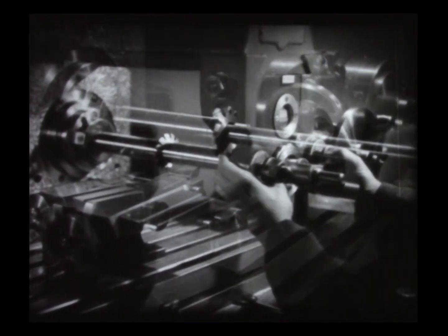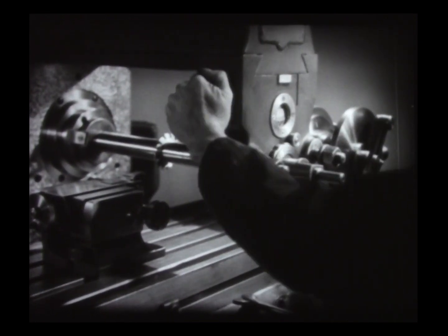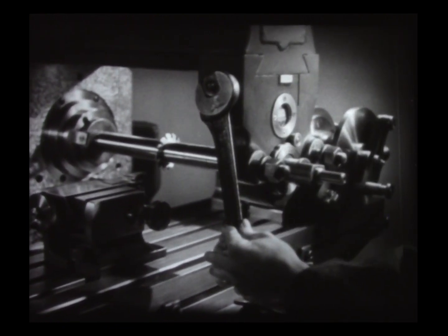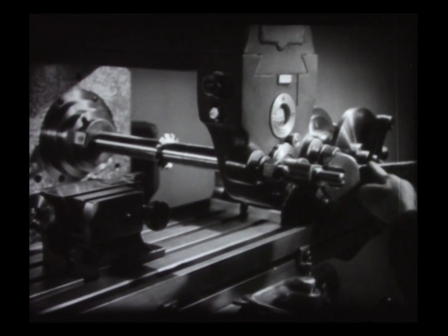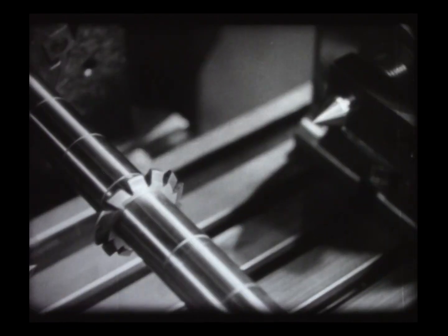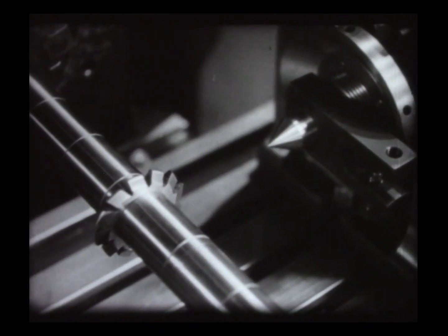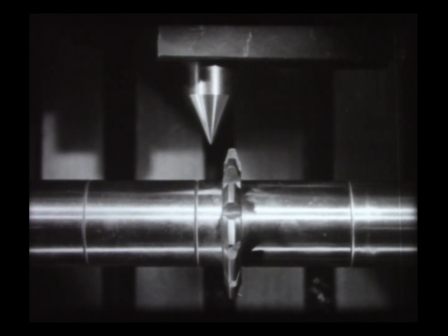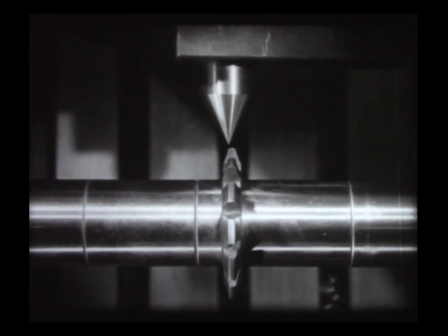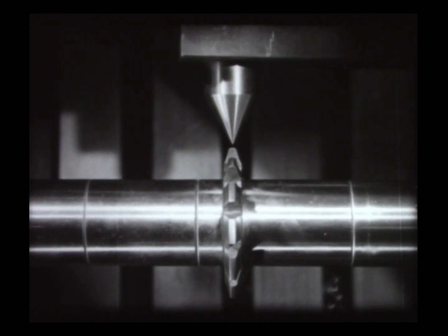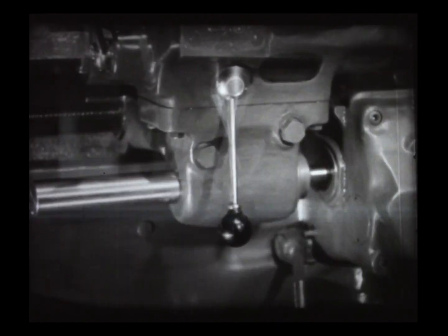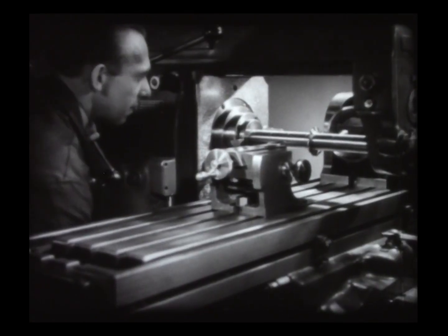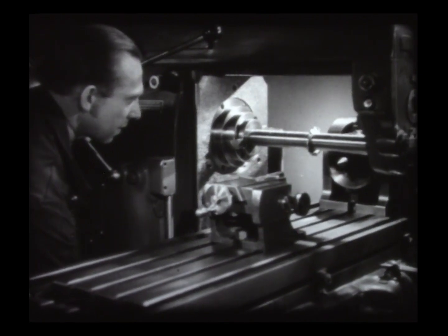After applying the key and the remaining collars and arbor support bushing, the operator rigidly secures the cutter setup. While there is still sufficient clearance around the arbor, the center of the headstock is lined up accurately with the center of the cutter. The centers of cutter teeth are marked for this purpose. The saddle is locked in this position. Next, the table is lowered to provide room for setting up the work.